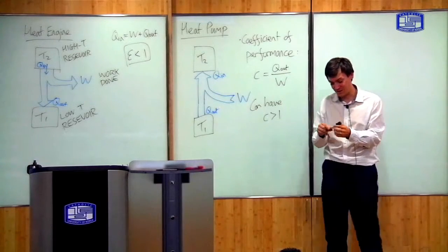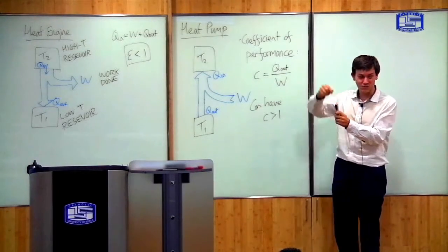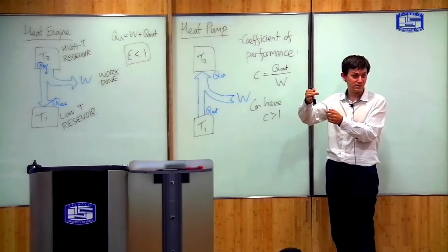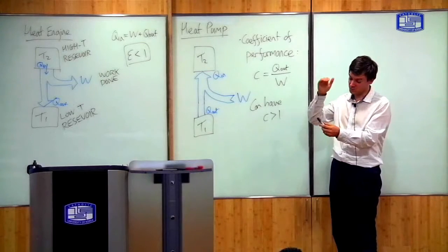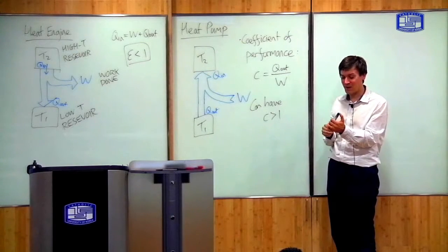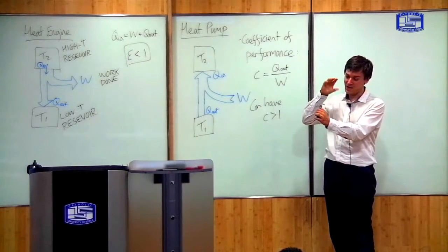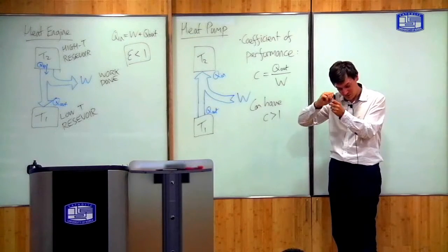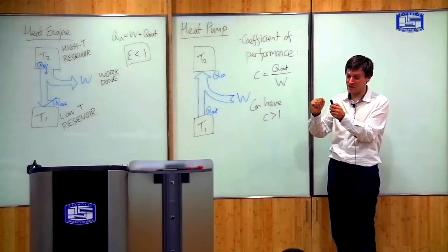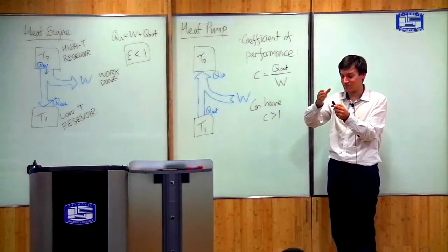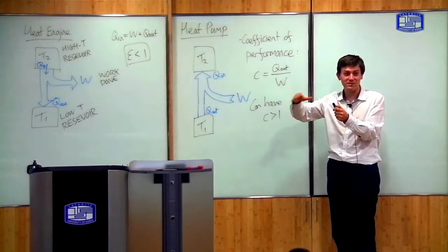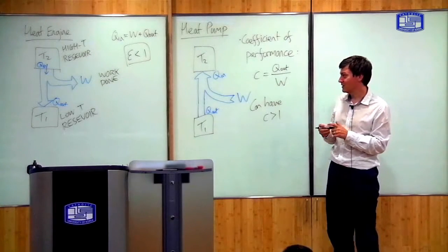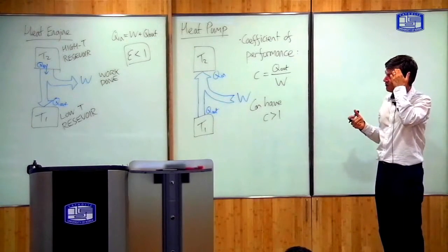You will also find that later on, if you let all of the air out of the tire, the valve will become cold. So these two facts: when you push gas into high pressure, it increases in temperature, and when you let it go from a high pressure place to a low pressure place, the temperature drops. Okay? This is known as the Joule-Thomson effect, and this is the basis of a refrigerator.